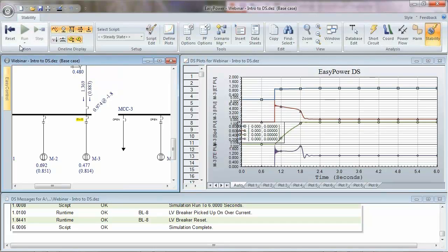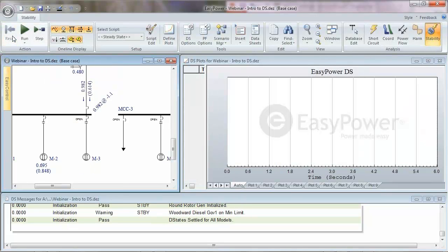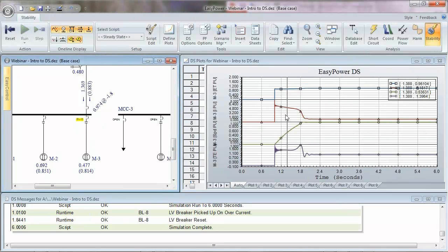When we're done, we want to reset to do something else. Well, we just reset our simulation with the reset key. So there you go. We have a quick addition of motor data right out of the library and a quick motor start. Now, if you noticed, I'm going to do this again. Notice how long the motor took to start. It wasn't very long. It's starting at 1 second, and it goes to roughly 2 seconds. So it's about a 1 second start.